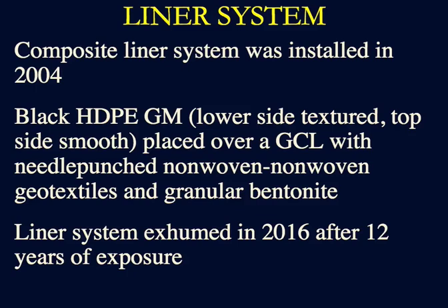The GCL was a needle-punched product which had granular bentonite that was sandwiched between two nonwoven geotextiles, and in cross-section was very similar to the GCL that Joe showed in his presentation earlier. The liner system was exhumed in 2016 after 12 years of exposure to the atmosphere.